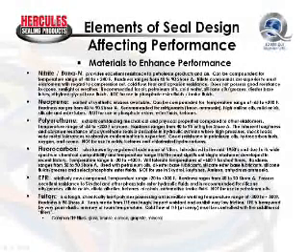And then Teflon. Teflon is not an elastomeric type of seal, but because it's used extensively for sealing applications, I included it here. It's a tough, chemically inert polymer. Working temperatures from minus 300 up to 500 degrees, and hardness usually around the 98 shore A. Teflon seals are tough, they're impact resistant, and they exhibit very, very low friction. They can be used on very, very smooth surfaces.